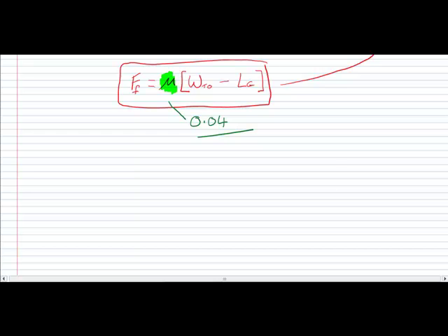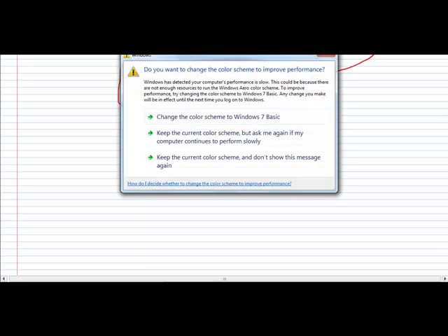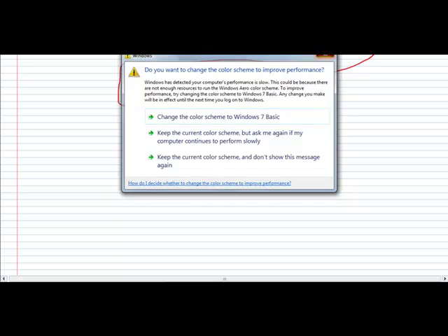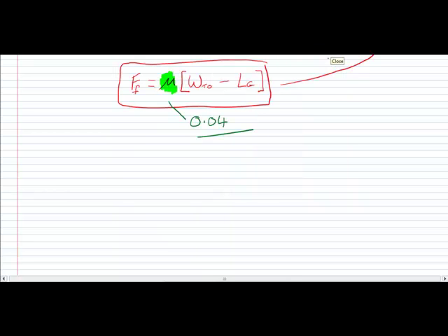It's trivial to work out the distance that the aircraft has travelled, and it's simply a case that the rotation distance will be 3 times takeoff velocity. Obviously you need to have your takeoff distance and velocity in appropriate units just to directly apply that formula, but it's literally as simple as that.